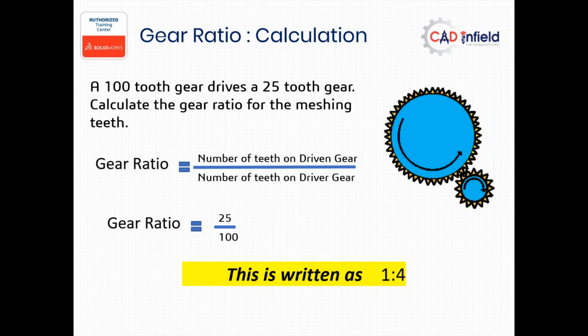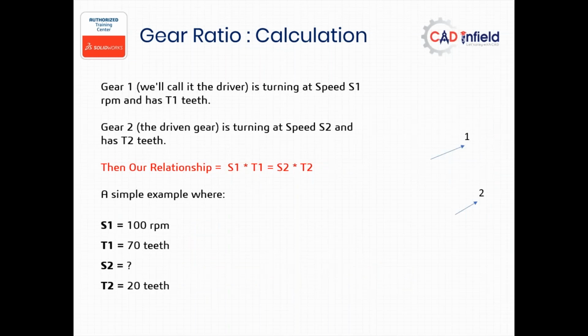If the PCD of the prime mover or engine is larger, we get the increase in speed. If the PCD of the prime mover or engine is less, we will get the reduction ratio. This you need to fundamentally understand. If you understand this, definitely it will be very easy for you.